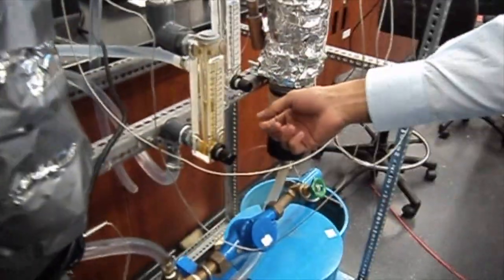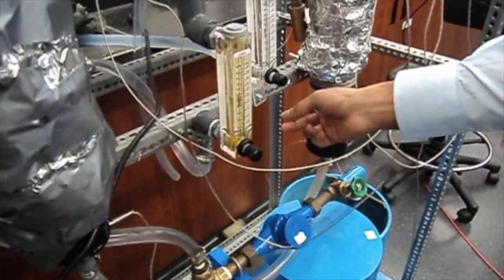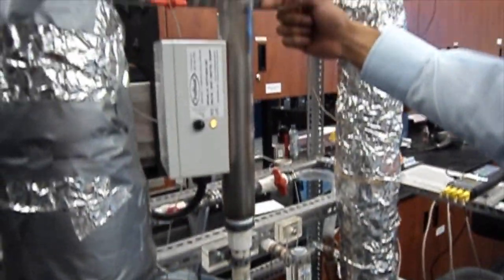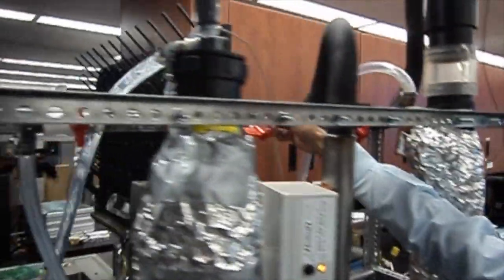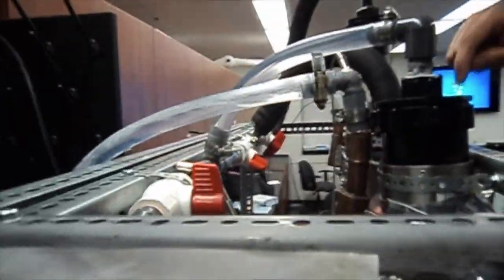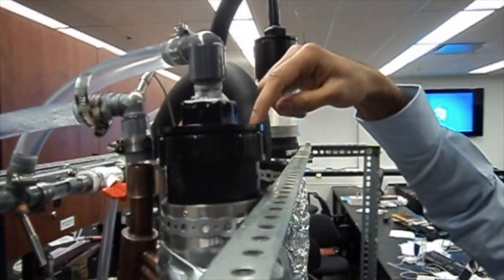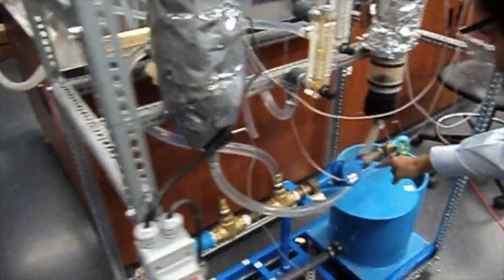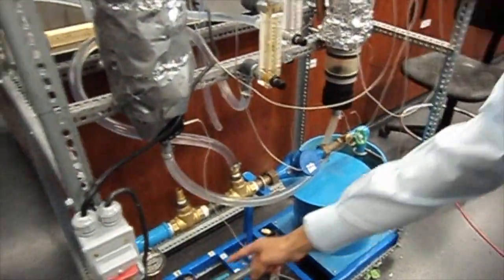This is an adjustable flow meter where flow can be changed based on the conditions that we want. And after the flow meter, it goes through this inline heater, over here, past these valves, and into the hot water inlet at the top of the heat exchanger. From the top of the heat exchanger, it creates a film in the heat exchanger, in the copper pipe, goes down here and back into the water reservoir, and then gets drawn in by the pump again,